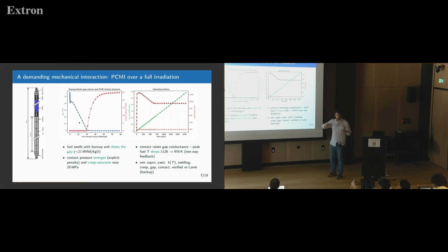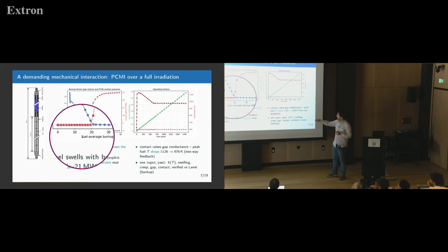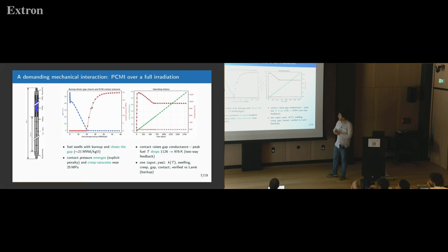are a bunch of nonlinear phenomena. We start with thermal expansion, then with some densification phenomena that are physical processes that happen in the fuel. But the point is that as the gap is closed, the two bodies are in contact, and there is a contact pressure, of course. Which may seem very obvious, but from a point of view of implementing and so on, it's very nice.